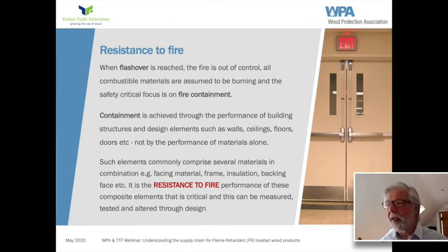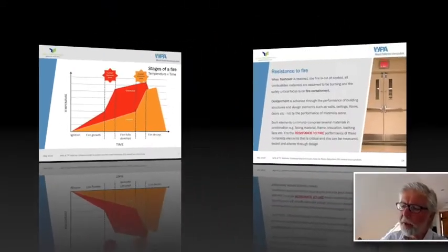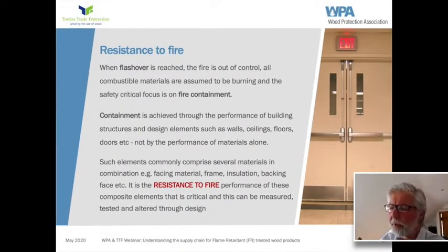Now, there's another term that I haven't mentioned yet, and that's fire resistance. If we think back to that graph I showed at the very beginning, we were talking about reaction to fire properties being the critical factors during the development and growth stage of a fire. Once you get to flashover point, the reaction to fire properties of the material become almost irrelevant. It's too late. And then you have to think about containment of that fire. And that brings in a different set of considerations, a different set of test methods.